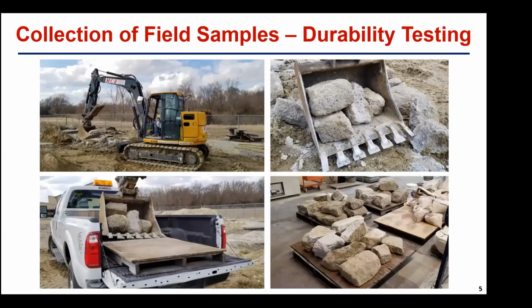So basically that was what was done, and just to fill you in with the details, basically we tried to core these test sections first and to try to get just cylindrical cores from the Quarry byproduct sections, but that was not very successful, because if we do a wet coring method, what happens is that the materials will disintegrate and we will not be able to get an intact core.